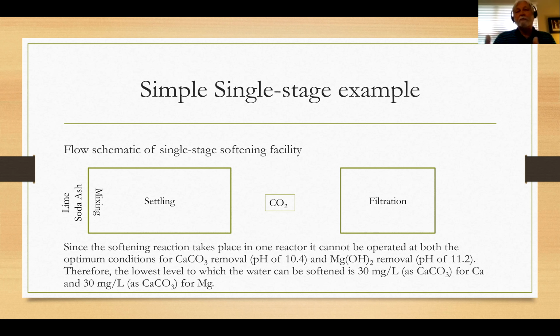You recarbonate, bring the pH back down, and any calcium and magnesium remaining, escaping the settling basin, you convert back to its soluble form so we don't make our filters the world's largest marble test. The sand media is not there, nor is the dual media there to precipitate your hardness on. So we need to recarbonate.